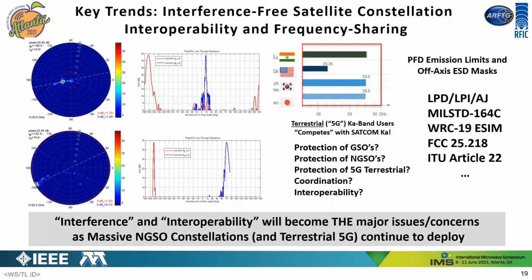As more and more satellites are using and consuming a limited amount of frequency band resources, the topics of interoperability and overall interference suppression are seeing increased concern and regulatory scrutiny. For example, we previously mentioned the Ka band frequencies with SATCOM terminals employing the 27.5 to 31 gigahertz frequency band for SATCOM uplinks. This 3.5 gigahertz of ITU band must be shared by all of the Ka band SATCOM systems. So that's including all of the various GSO constellations from Hughes, Viasat, SES, Telesat, and others, but also NGSO users, including Telesat, SES, O3b mPOWER, Kuiper, and others.